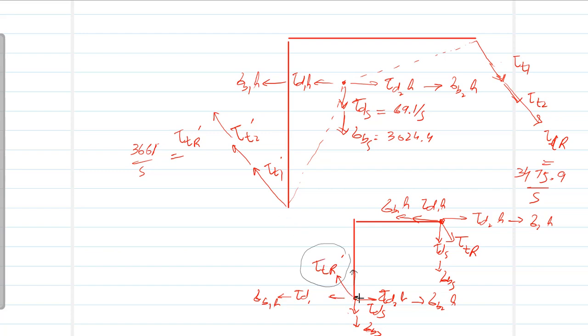Why? Because one of the torsion shear components will be subtracted, and that is generally the case when we have more complex geometry. You can find it from any point by just assuming that at this point, let's say I call it point A or point B. This is point A. This is point B. I can argue that at point A tau TR is in the direction of the other stresses, whereas tau TR prime is actually in the opposite direction, and that causes the stresses to be low because stresses will be subtracted. So I just take this point to find the size of the weld.